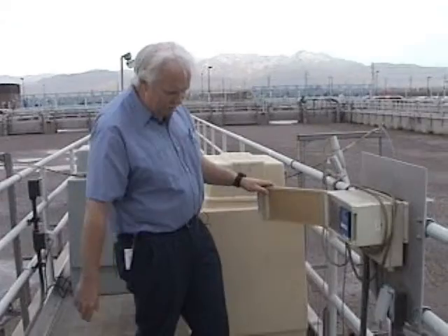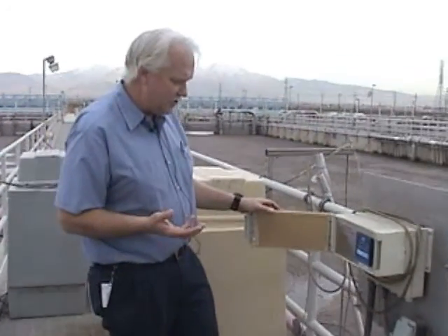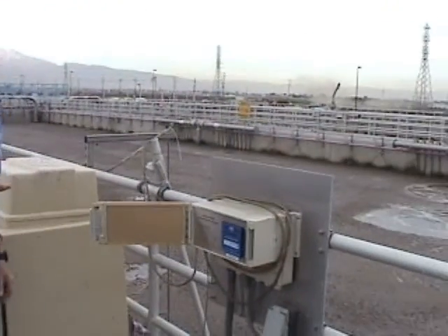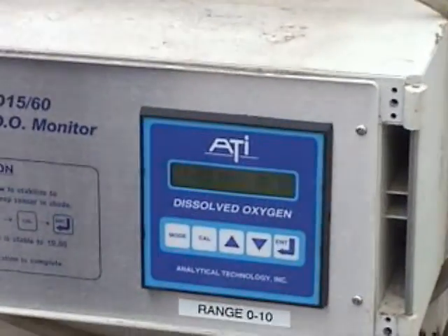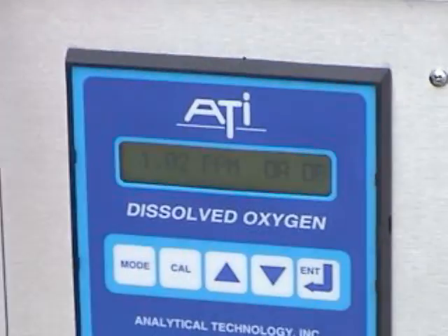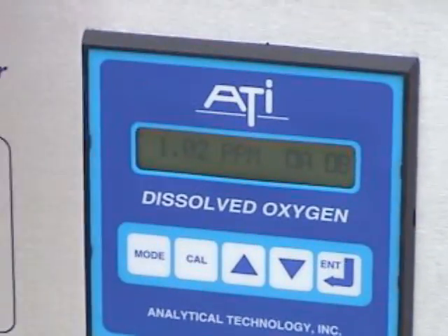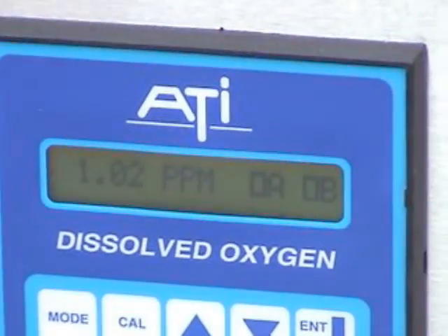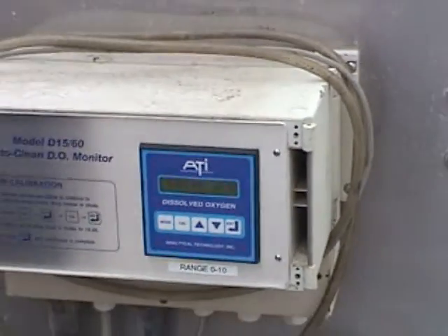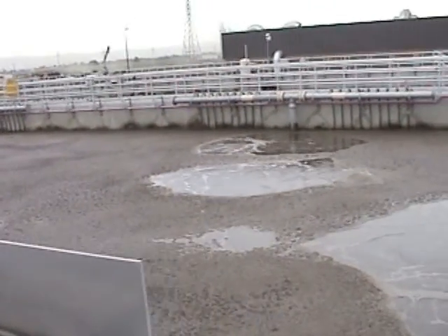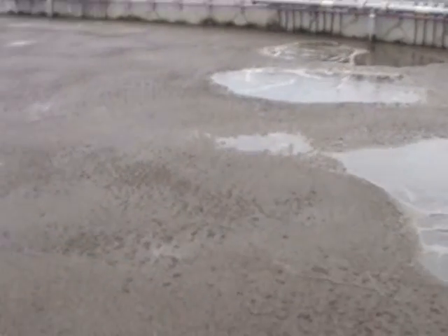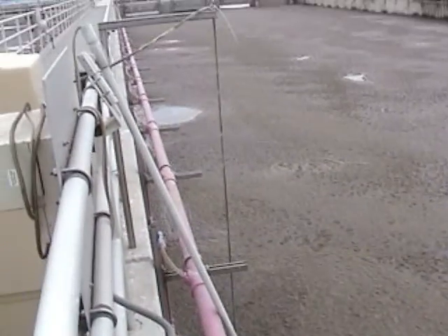For operators, the only responsibility they have with this is that we're taking down the DO every day and entering set points into the computer system. Like if we have a set point of 2.0 for an aeration basin, what we'd expect the operator to do is compare our set point to what we actually have on the system. If we're not meeting the set point, we need to have instrumentation take a look at the probe and make sure that it's a valid reading. These do require periodic calibration, and the instrument techs will handle that.